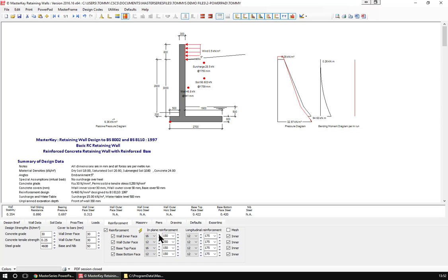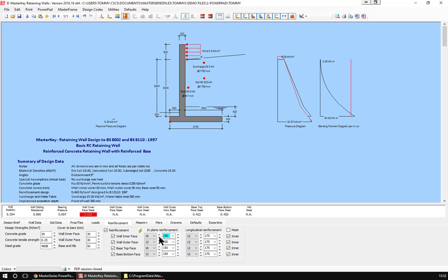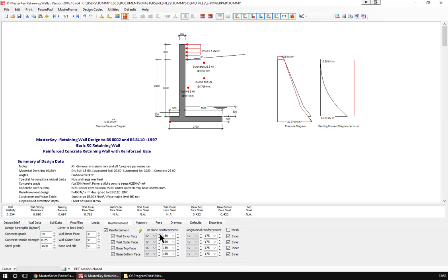16s is going to work well. So 12s at 150, 10s at 150 isn't good enough. So 12s at 150 would do the work. And what have we applied? We've applied a wind load because we've got an upstand on the wall. We've got a sloping back. So we can apply all those things to our wall. Grade 30 concrete. That will be the cube strength.